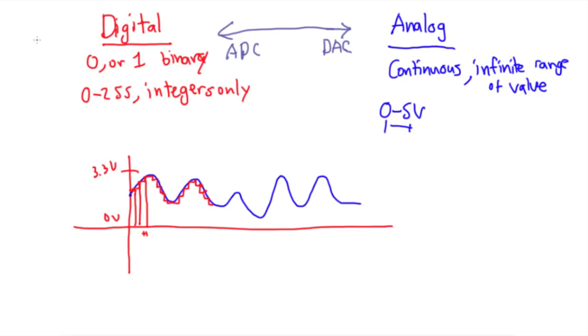So in the case of the microcontroller, we have a 12-bit DAC, sorry, not ADC. This means it can output something within this range of 3.3 volts, and each of these little steps is what it can become. So that's effectively how the digital to analog converter works, pretty much in the same way.